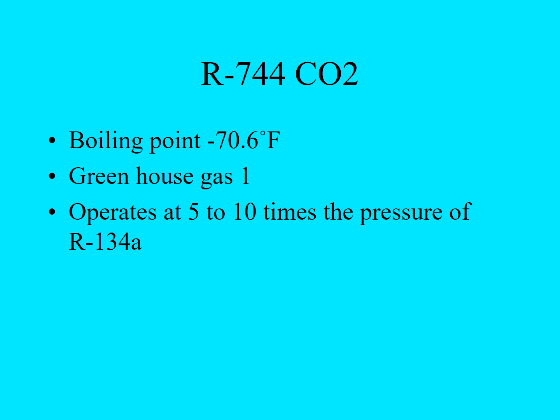So because of that, the components that would be used in a R744 system would have to be much stronger to withstand the pressures being used in that refrigeration system. At this point, no domestic manufacturers are using CO2 as a refrigerant yet.